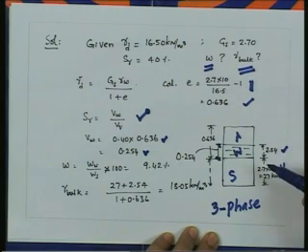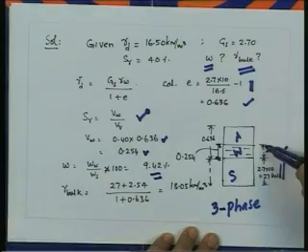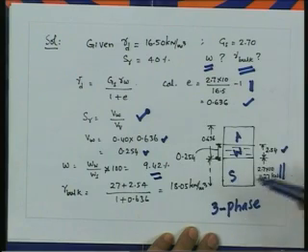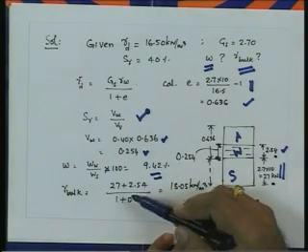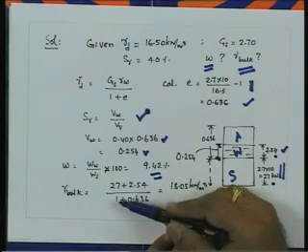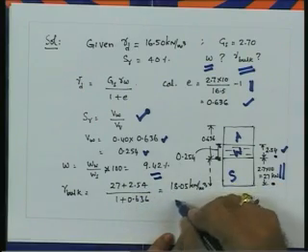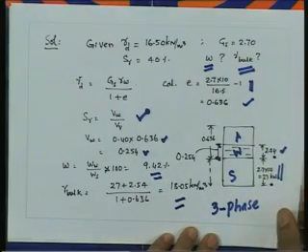From the definition of water content, w is equal to weight of water to weight of solids into 100, we can get the water content for this given problem as 9.42%. The gamma bulk, the bulk unit weight of soil mass, can be deduced as total weight to the total volume, that is weight of solids plus weight of water to the total volume, that is 27 plus 2.54 divided by 1.636, that is 18.05 kilonewton per meter cube.